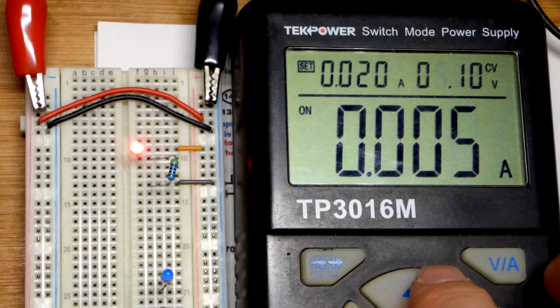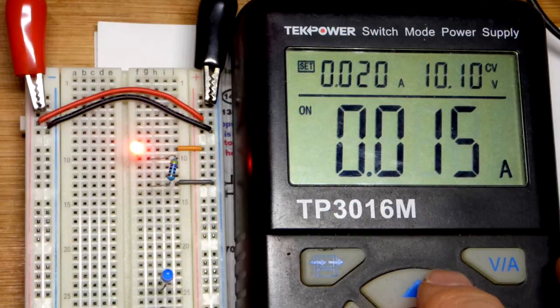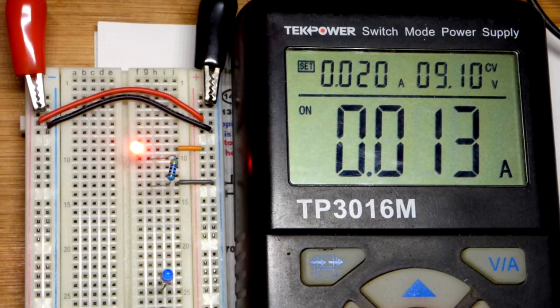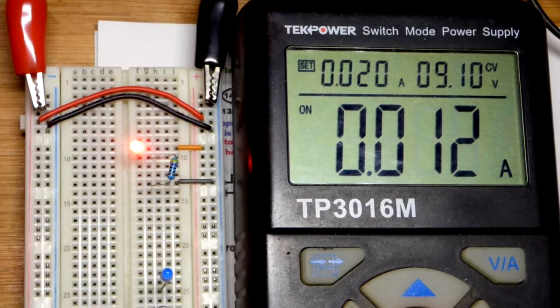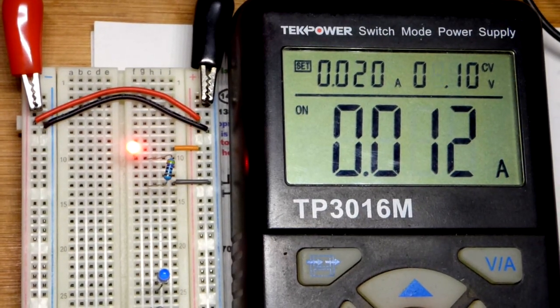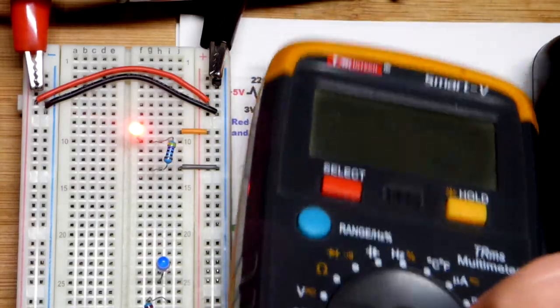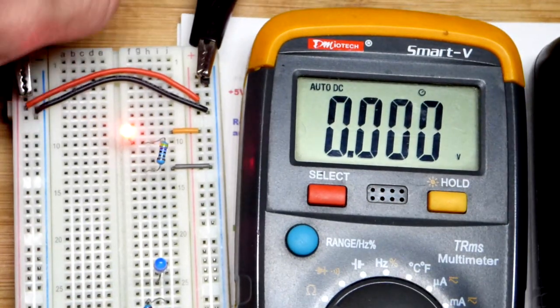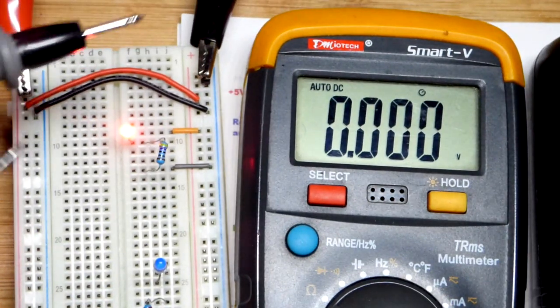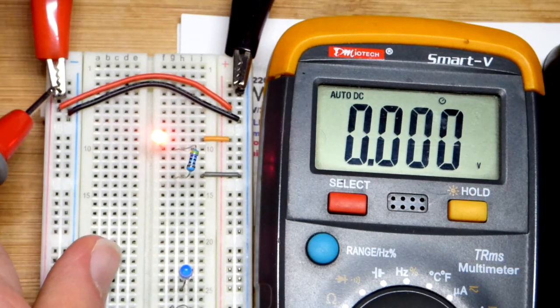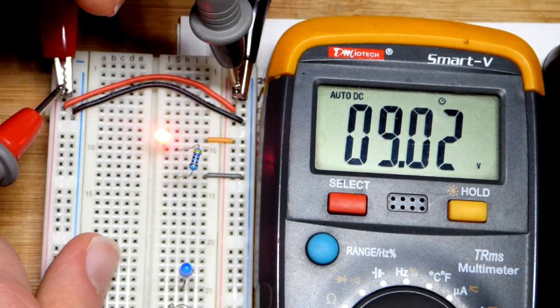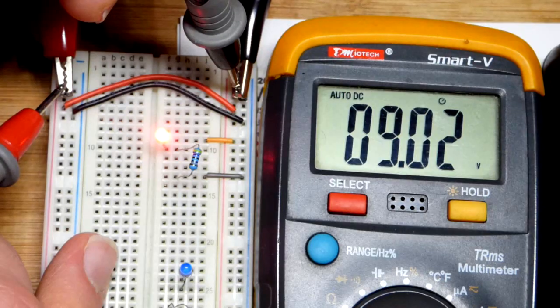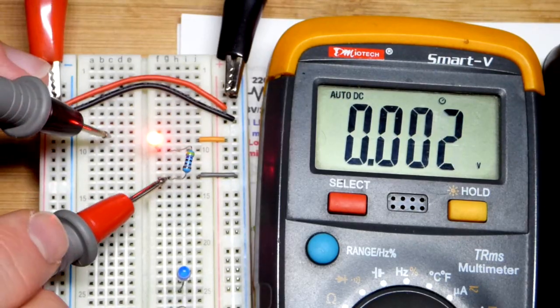So we have a 470 ohm resistor protecting it. We can bump the power supply up to 9 volts. Even 10 volts wasn't terrible. But in any case, 9 volts there, somewhere around about 13 milliamps of current flowing through the circuit. So again, right from the start, you want to get multimeter practice. So we set to V for voltage. Don't have to move the red probe or the black probe for any of this. We can measure the supply voltage at the alligator clips, and that's going to give us our highest measurement right there. Or we can measure it across the load.